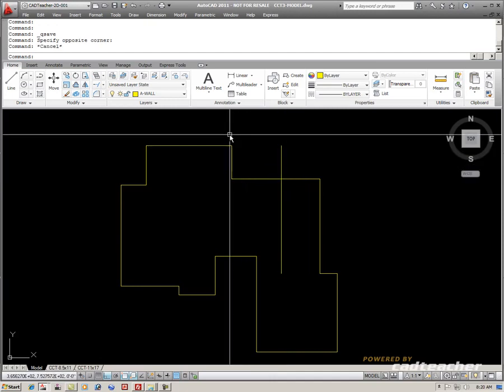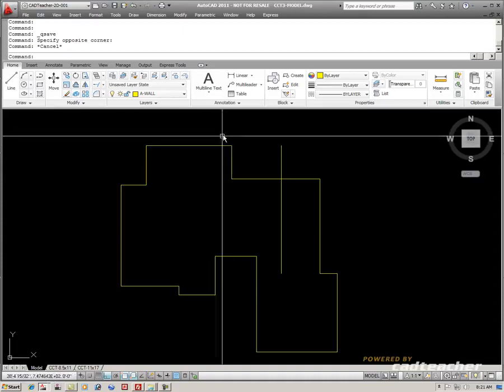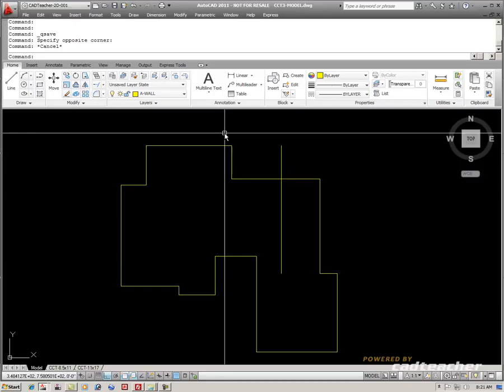Now, I understand that most of the walls we normally build are 3.5 inches for 2x4 studs or 5.5 inches for 2x6 studs. But just to make your life easier, when we draw our walls, we will be using 6 inches for the walls. So right now I'm showing the outside perimeter of the house. What I'd like to do is to take these lines, join them into a polyline, and then offset these by 6 inches on the inside.